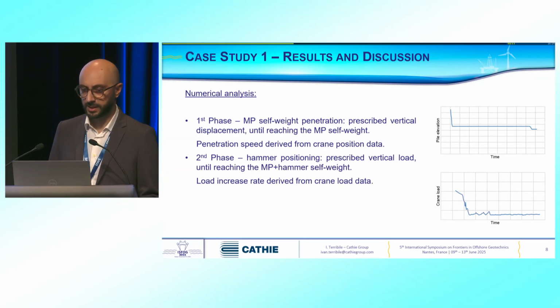The second phase simulates the hammer positioning. During this phase, the monopile is not restrained by the crane. It is free to accelerate under the hammer load. So a load controlled analysis was performed. Both the load increase rate and the displacement rate imposed were derived from the crane data.